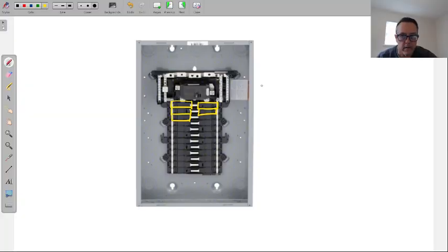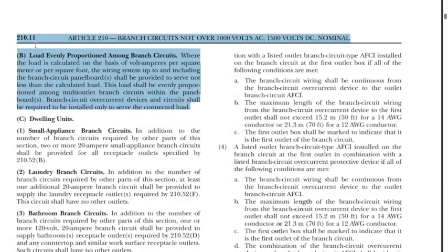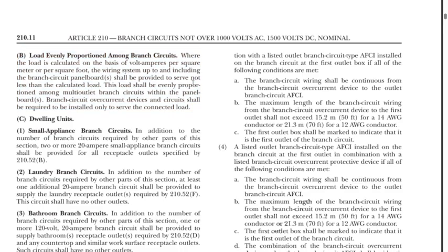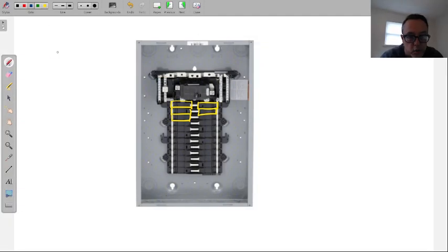What you have to do here now, because of what it is saying, is to evenly proportion among the multi-wire branch circuit. In other words, distribute this load amongst the circuits. Of those 62, you don't put 60 on one, hypothetically, and 2 on the other. So to your question about 40 on one, how do we do this with outlets? Because I don't know what people are going to plug in where.